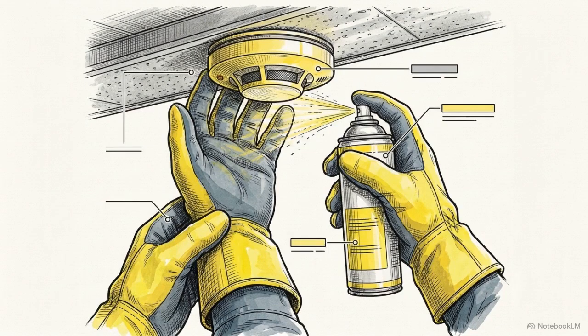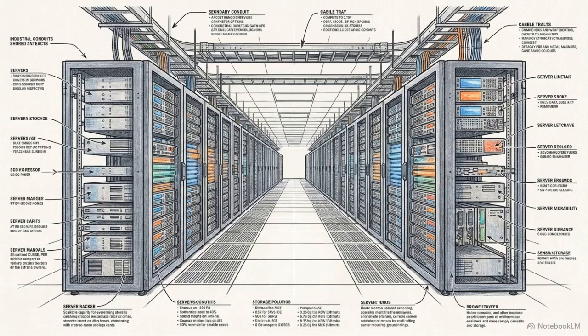It requires strict sensor selection, like deploying heat detectors instead of smoke detectors in commercial kitchens, and rigorous biannual testing schedules under standards like BS 5839. A system that cries wolf destroys its own operational value. Deep integration with building systems demands zero false positives.